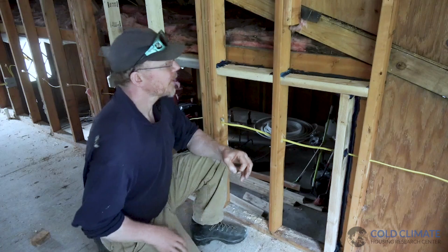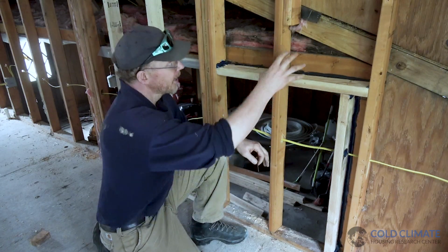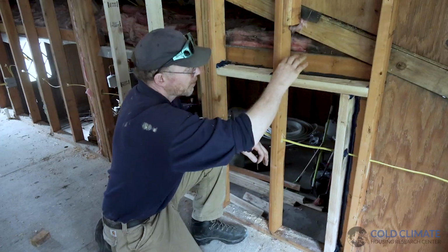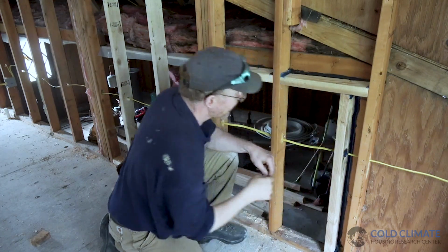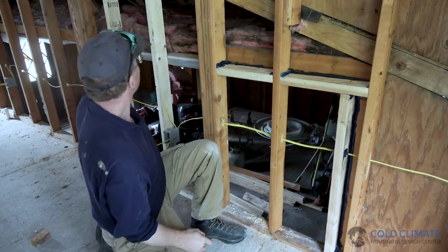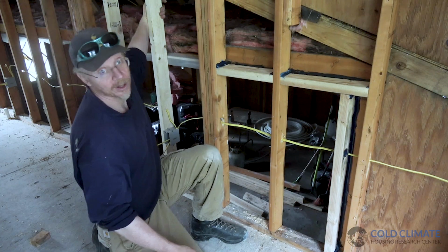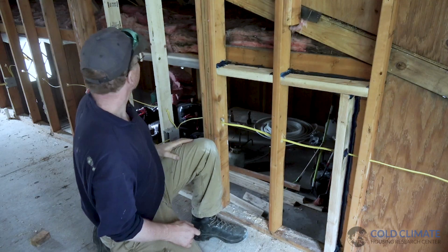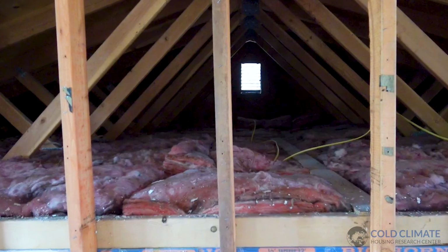As I mentioned earlier, a spray foam contractor is going to come onto this job site and then fill each one of these bays and seal against these blocks, as well as seal inside this area and all the way along. The spray foam will also reach the back sides of these studs and encapsulate everything. So that will add additional insulation, and there will be more insulation blown into the attic.